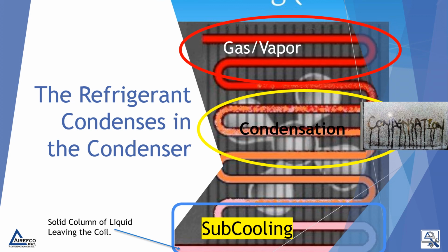In the last portion of the coil, the liquid refrigerant is further cooled by removing more heat from the refrigerant, which is our subcooling, to assure that we have a solid column of liquid leaving the outdoor coil heading to our metering device.